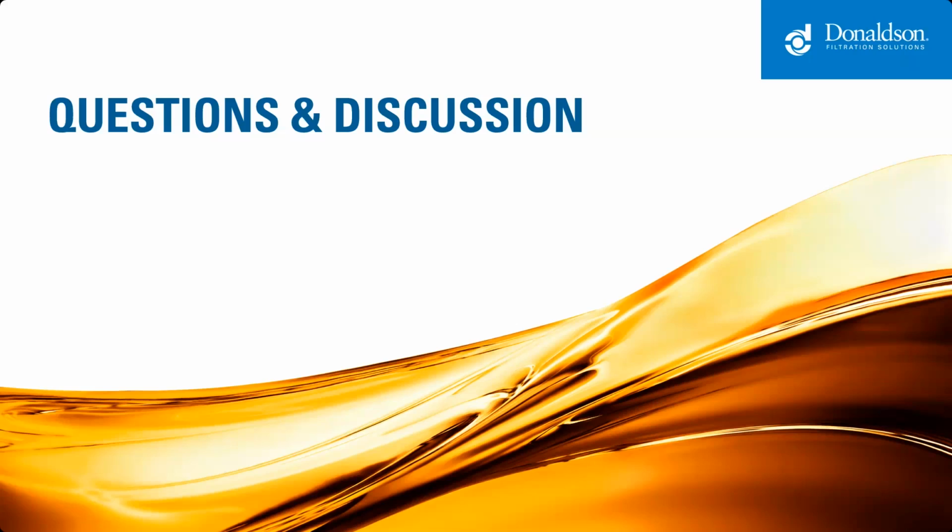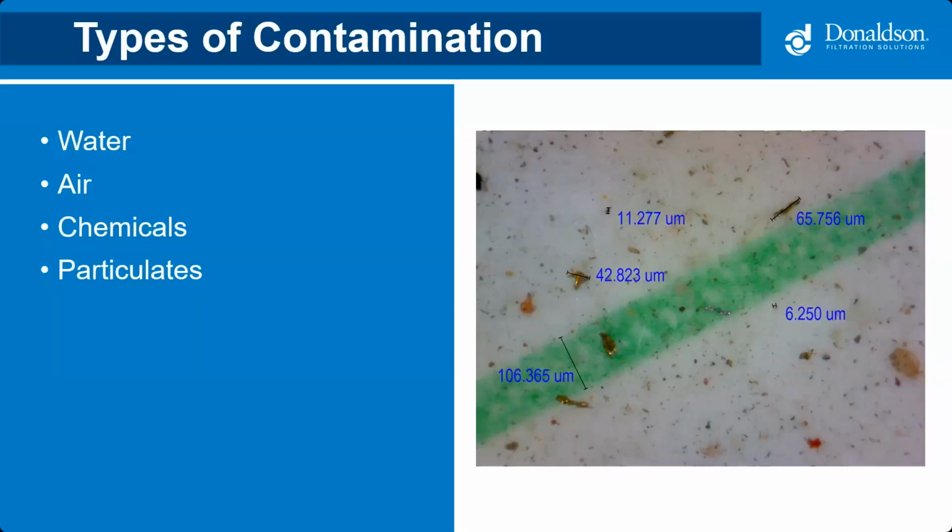Yeah, let's start, I guess, with water. When we look at water within a circuit, there's quite a few different things that can occur. Water, one, is compressible a bit. And so if you have water within a hydraulic circuit, you will get a little bit of squishiness potentially in whatever you're trying to operate, especially if it's a cylinder-based circuit.